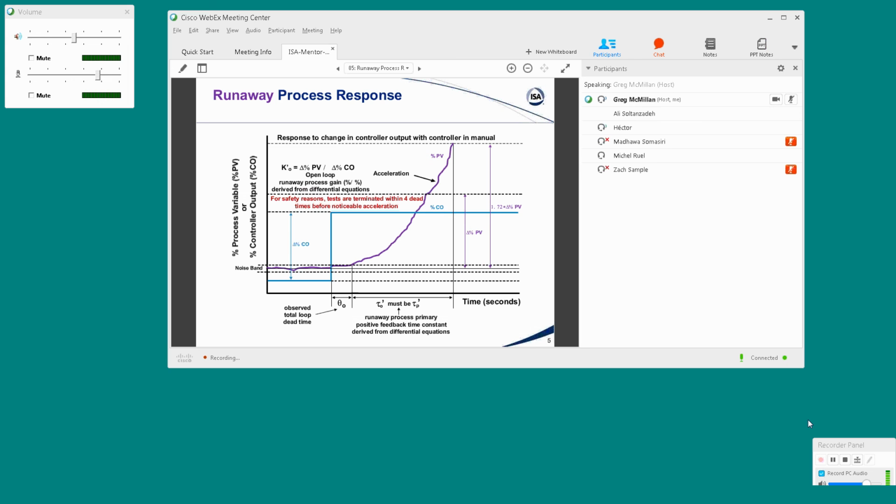And we'll get into this, that actually what Shinskey would say, and many others in his thinking would say, is that you want to tune for load disturbances, because if we didn't have load disturbances, why would we need control loops, really? But you have the load disturbance, you want to address that first. And you can get the set point response you want, which we'll see, by the use of different PID options, like PID structure. And he would say putting a lead lag on the set point. So you can tune for load disturbance and then still achieve the desired set point response in terms of minimizing overshoot by some use of PID options.